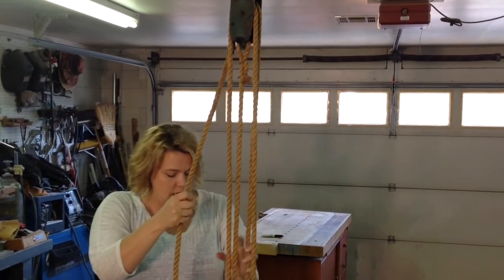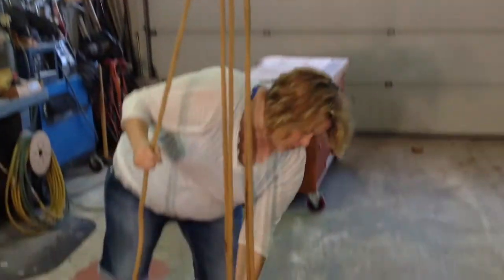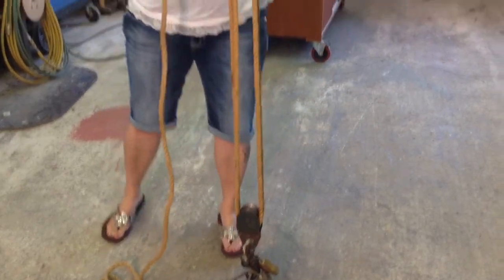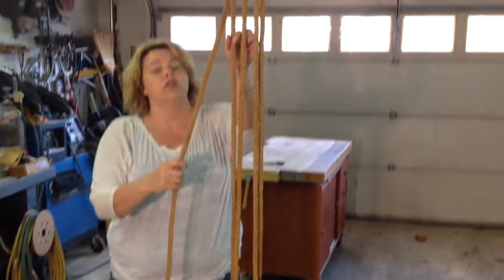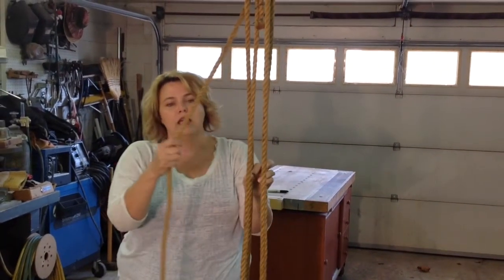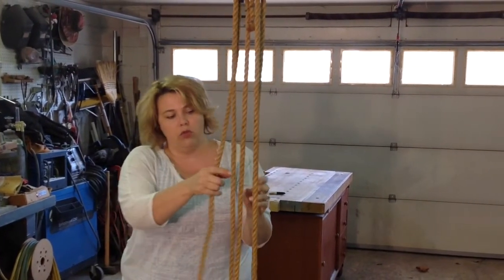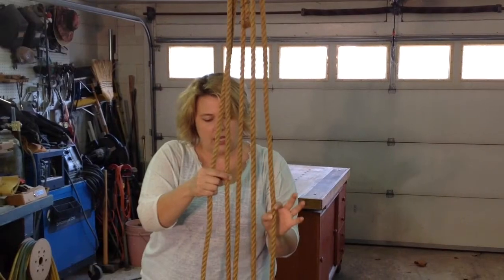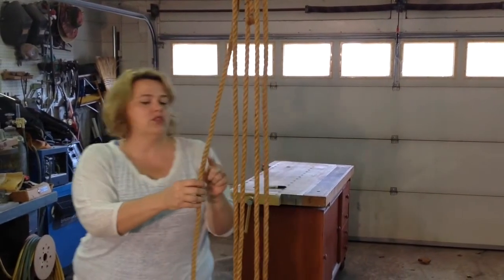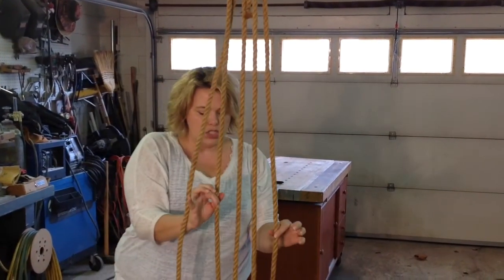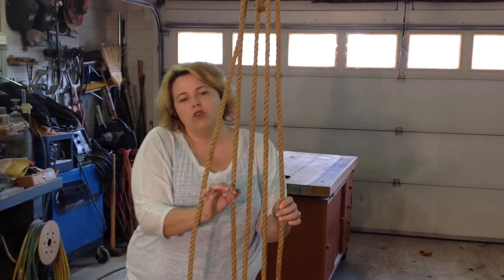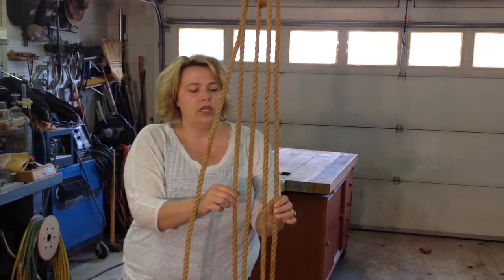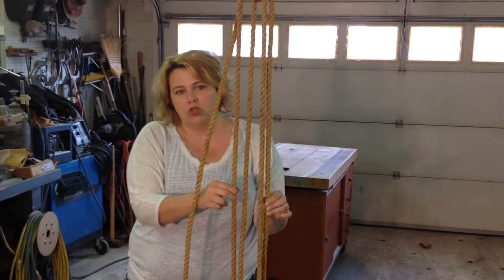Kind of like the same thing, if I only had the pulley here in the back, where it goes up, over, around, that would be an example of a movable pulley, where if I just had 2, and then this one would just be changing the direction. So if I just had 2 strands supporting a weight, we'd have like a movable pulley, and then that would be a mechanical advantage of 2.